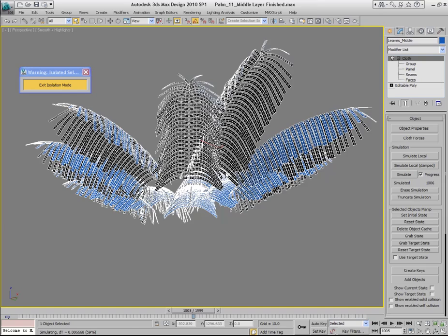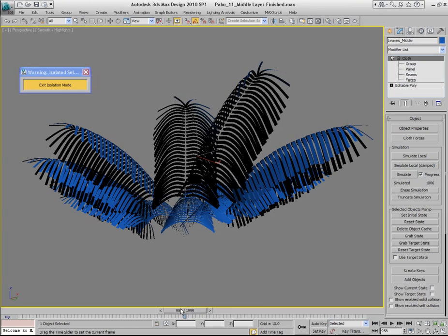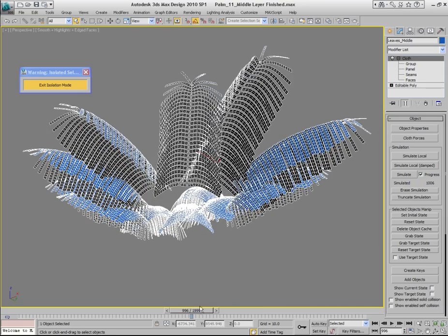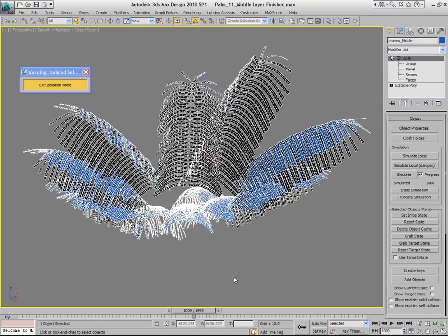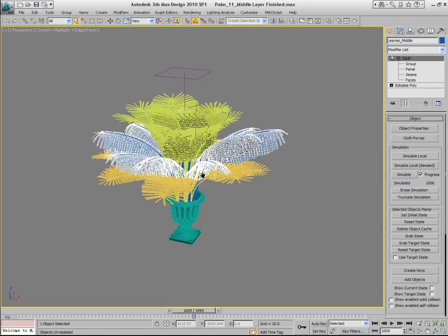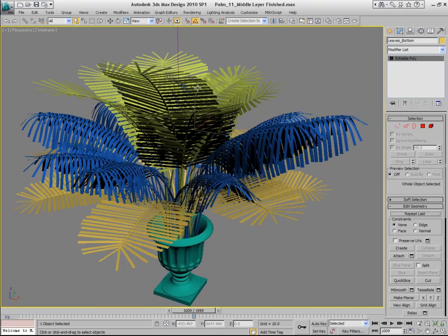Okay, we can click cancel now, and we only need 3 or 4 frames, because you see, once wind starts participating in a simulation, it brings distortion to the subject real quick. So just a few frames is enough. See, that's pretty much what we want, and you repeat this procedure for other layers of this object, particularly speaking, this bottom layer and this top layer.